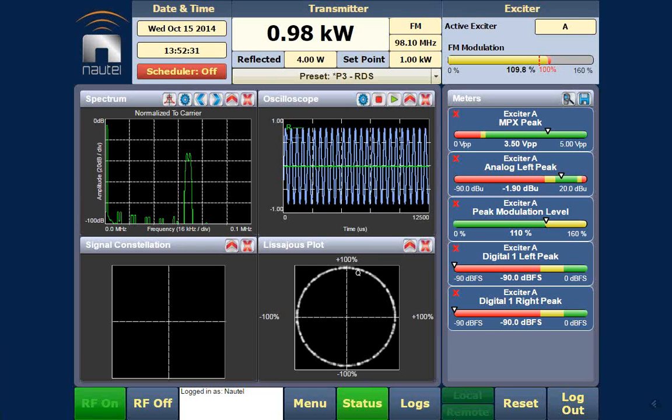So what we've done is it really didn't make a lot of sense to force the user to leave remote mode to go to local mode when they were on site. Because the risk was many customers would forget to put it back into remote. Now, we've made lots of recommendations where users should put a big light bulb, and now you could use your site control function to drive that light bulb based on the remote status. It just reminds you to put it back into remote. But we really didn't think there was a huge value to it. The real value comes from being able to disable remote. That way those remote users have no control, but you always have local control, because it was really as simple as putting it to local to get local control. There were really no other locks or measures.